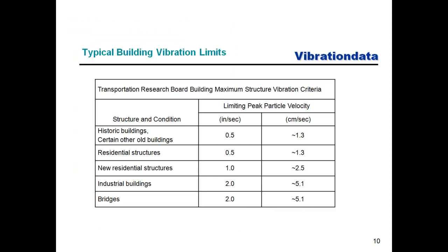Okay, here's some typical building vibration limits. For example, if you had a charge mode piezoelectric accelerometer, you could mount it on the floor of a historic building, and then you could take that signal through the Brüel and Kjær 2635 charge amplifier and get the velocity output. Or if you just have an acceleration time history measured via a different measurement system, there's different post-processing digital integration that you could do as well. We'll be covering that here shortly.